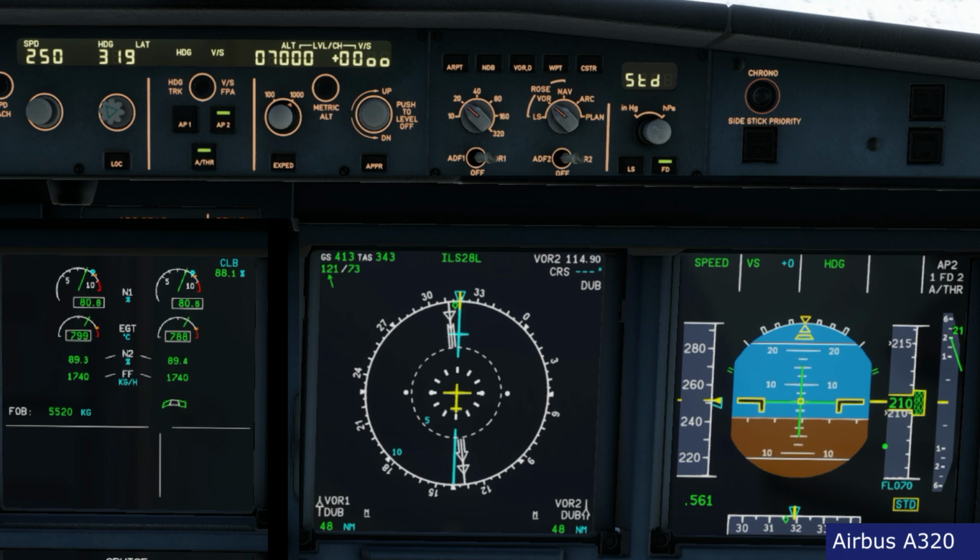Actually, it's not exactly the same function, because if you remember, what the altitude hold did on the 737, and it's what the alt green does on the Airbus, is to memorize the altitude at which the mode has engaged and to maintain that altitude. So the 737 would descend back to the altitude. What's happening on the Airbus is that you just select a vertical speed of 0, so we are maintaining the altitude via a vertical speed of 0 feet per minute.